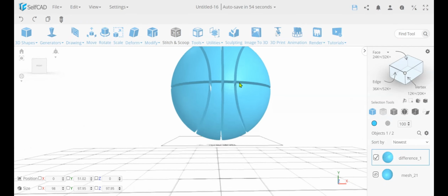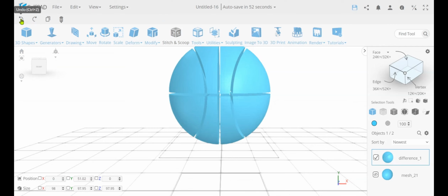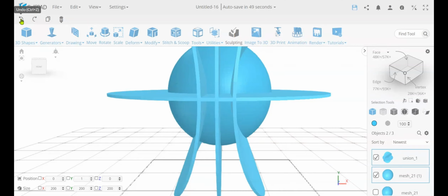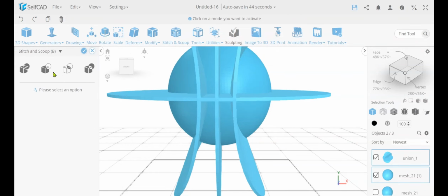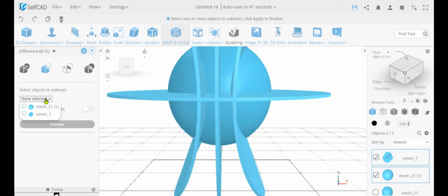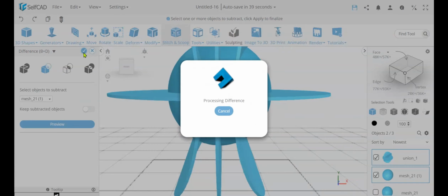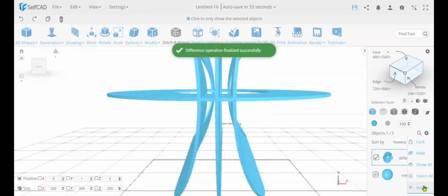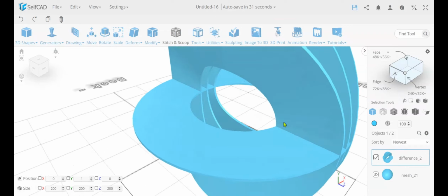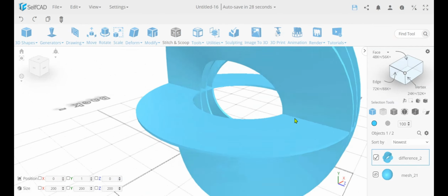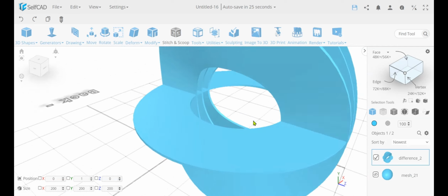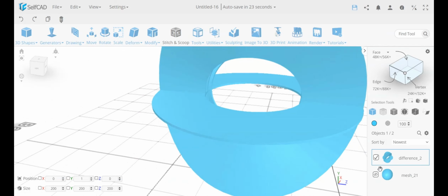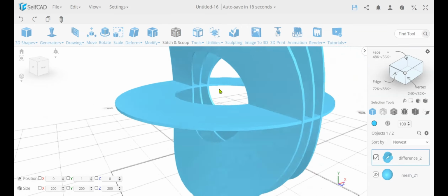It basically slices this. And what I did afterwards was, instead of removing these pieces, I removed the cylinder from it, and I was left with this piece over here. Let me isolate this, you'll see. What I did is I made these holes. So that's basically the way I did it. So you get these holes. And once you have these holes, because I made it 98, the hole over here is just 98. And if I put in the new cylinder, the original cylinder, which is 100, then it will stick in by 2. So you have an exact precise cut.